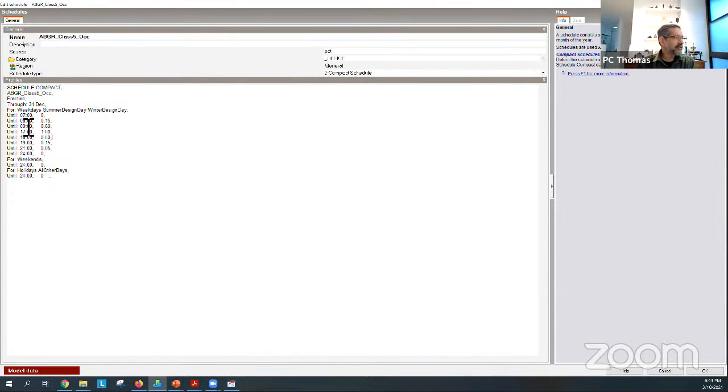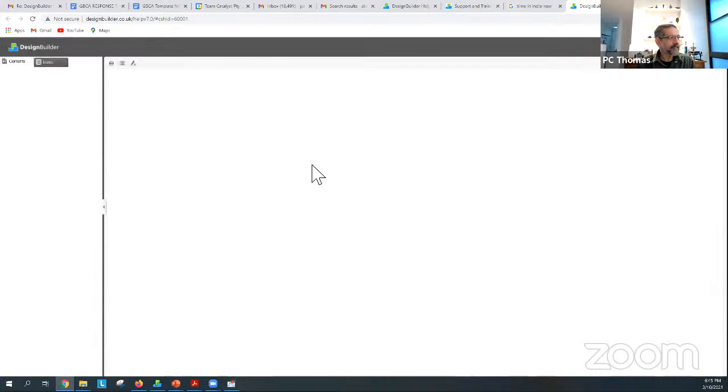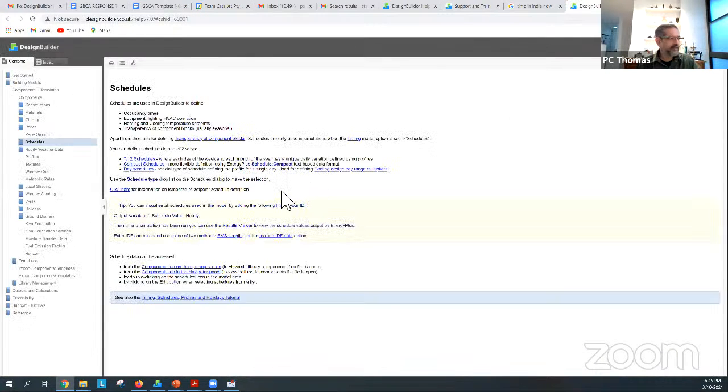There's colons, commas, and then after I finish the weekdays and the summer design day and the winter design day, I've given it for weekends. I've said holidays, and then one reserved term is all other days. So if I missed any day and it comes up in the simulation, then use this profile. Okay, and right at the end, there is a semicolon. Now, don't be worried. There is a lot of information available for you. If you click on the help part of it, it gives you a good set of examples.